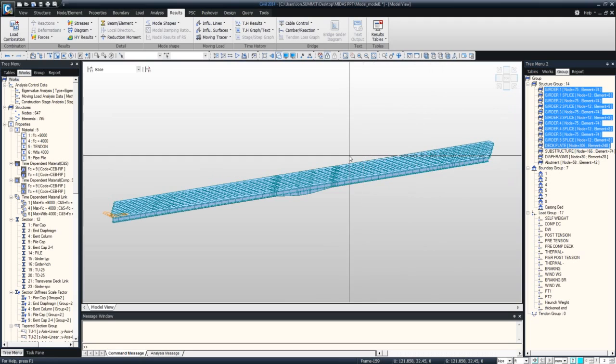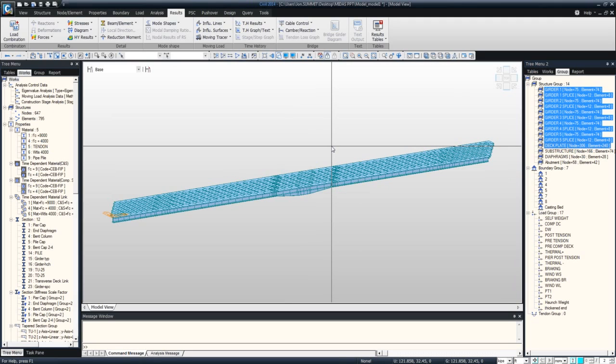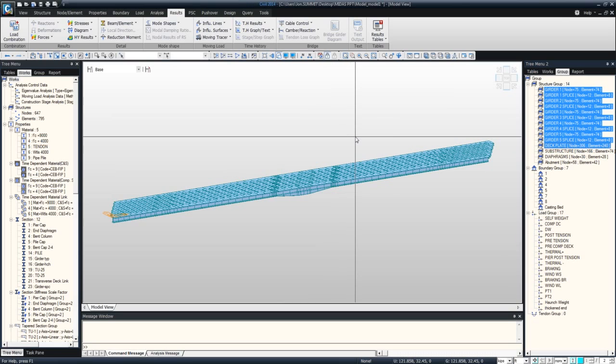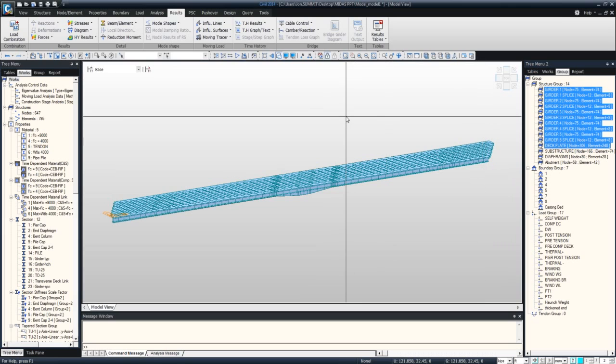And in addition, the composite element allows the moment and axial force times the moment arm, which is in the deck element, automatically to be transferred to the composite section to allow for more refined and more streamlined analysis and load checking.